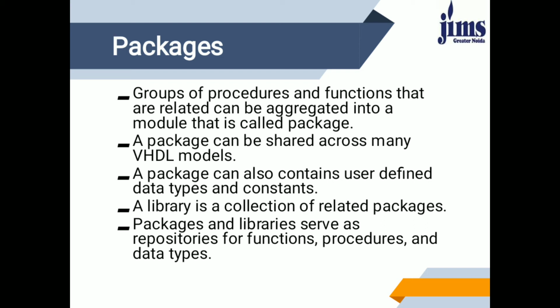Packages are concepts introduced in VHDL allowing reusability and sharing of code across different design units by providing a modular storing mechanism. A package can be defined as a collection of components, functions, procedures, data types and other design units stored conveniently in a design library, so that any piece of code required by any design unit can be called and reused from the stored module instead of being rewritten every time.